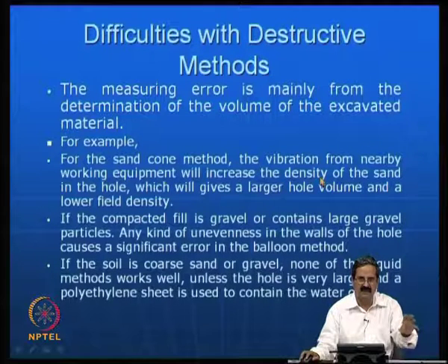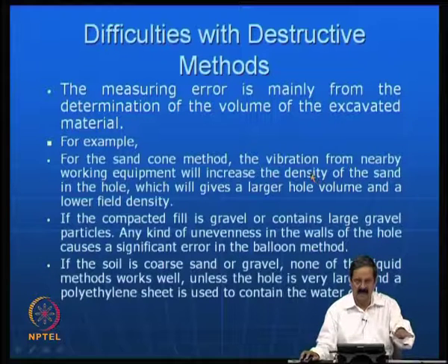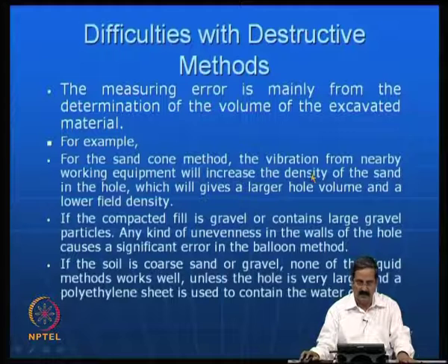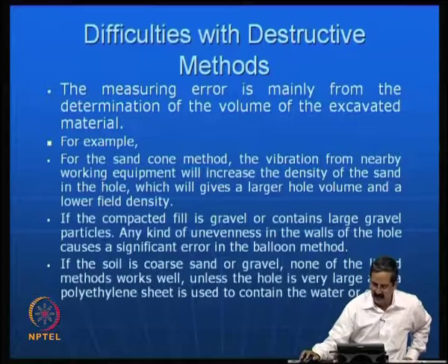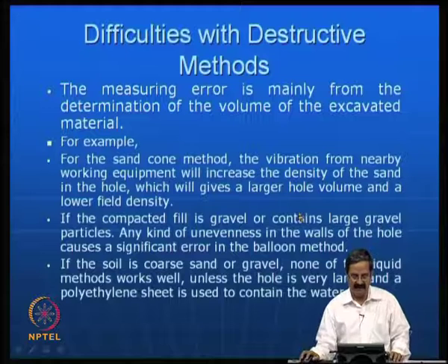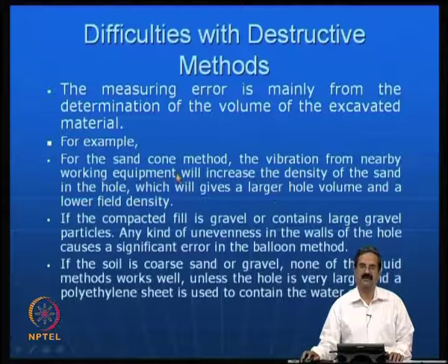The moment there is a vibratory equipment next to a sand material, the compaction is likely to be better, and that is one possibility. There could be even dilation also. So, it depends on the type of vibration that they have, and one needs to be careful. This may lead to minor errors.